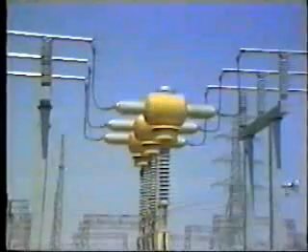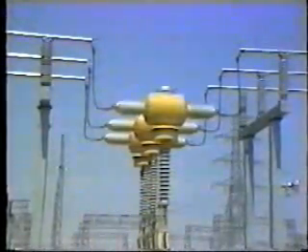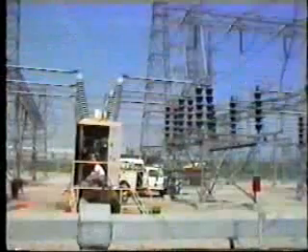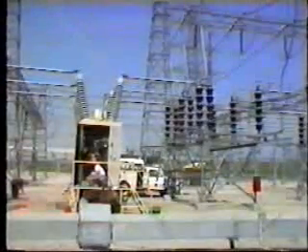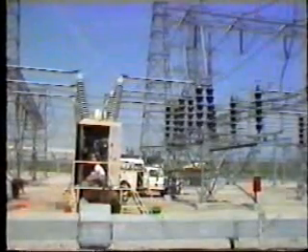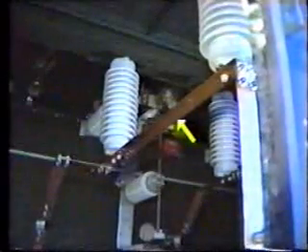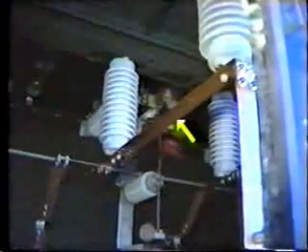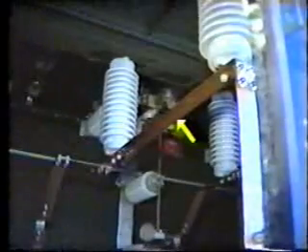At various points along the bus, transmission lines or other circuits are connected through circuit breakers. Disconnects are provided on either side of the breaker so that it can be isolated for maintenance. At lower voltages, the bus may consist of solid copper bars running inside metal-clad enclosed switchgear, which may be built indoors or outdoors. In this arrangement, breakers can be disconnected from the bus in order to isolate them.